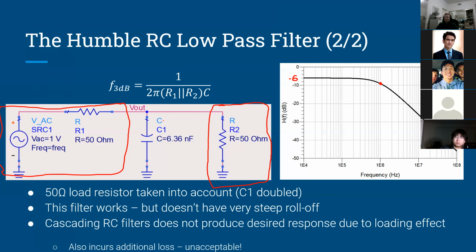Is it because of the voltage divider, R1 and R2? Right, exactly. So if you imagine, take a look at DC, for example, 0 frequency. You can ignore this capacitor because it's open circuit. So we get 50 ohms in series with another 50 ohms, and that just gives you a voltage division by 2. And remember that the 2 in dB scale, you do 20 log 10 of 2, and that comes out to roughly 6. So that's why we're at -6 dB at low frequencies.